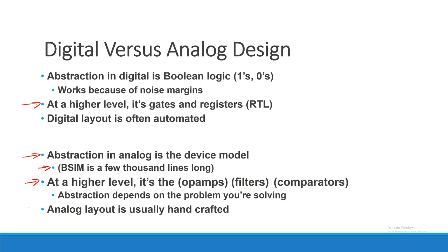Okay? The other thing, of course, is just from a design standpoint, analog layout usually is very meticulously handcrafted. And we'll actually talk some more about some of these tricks and rules that you need to follow to do that. But very, very rarely is this ever generated by you pushing a button. It's usually you sitting there, and you move that little piece of poly, and you move the little diffusion, and you try and really craft it down to that last little detail. Okay?